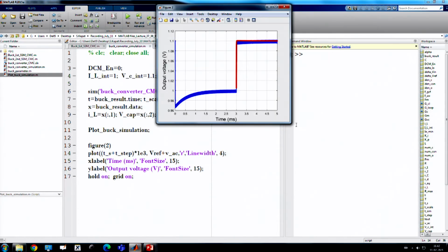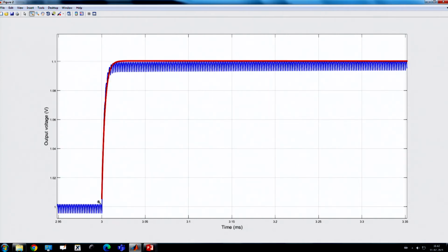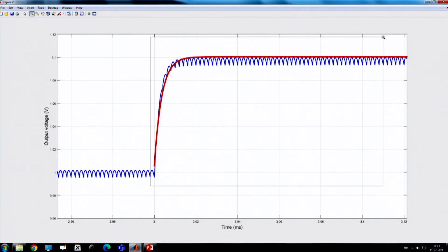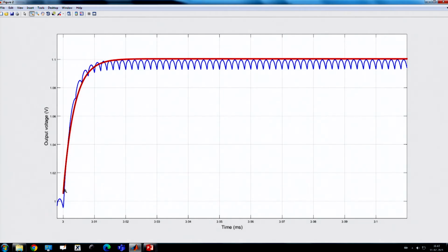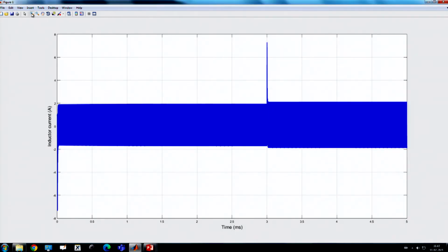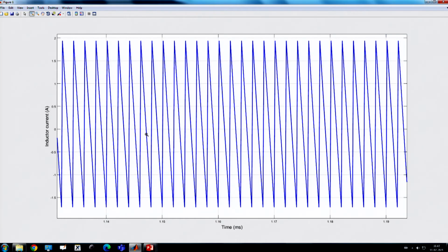Now, it will show all the bandwidth, okay. Now, this time the model is matching to some extent, except there is a shift in the DC value. That means, you see there is a DC shift, the red color is shifted up slightly, okay. So, this DC shift is coming because of what? Because if you go to the current waveform, you see we have taken that peak current, we are controlling peak current, but we have assumed the control current is equal to peak current, right.